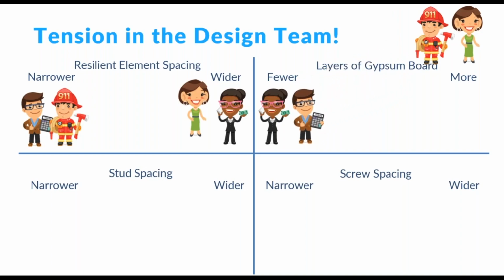Structural engineer. Now this one may or may not make as much sense, but structural engineer often will actually want fewer layers of gypsum board. There was a project that we were working on not too long ago, I think it was out on the West Coast where seismic is a big issue. And in this case, the structural engineer was looking at the mass of the gypsum board, especially higher up in this building, because that was going to increase this inertial mass that was moving back and forth in a seismic event.